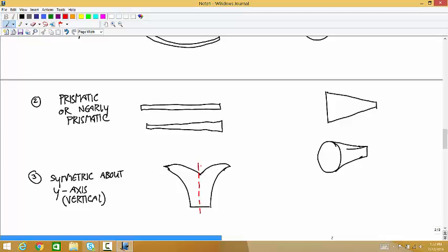Question? Couldn't you rotate your axis? That's an important question. No. So when I say the vertical axis, what I mean is symmetric about an axis that has this relationship with the bending axis. All these calculations we're doing are assuming that the bending is about the z-axis, and the x is along the long axis of the beam. So it's not really being vertical that's important. It's the relationship between this axis of symmetry and the axis of bending. But that's a really important point.